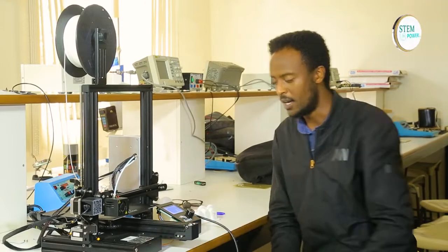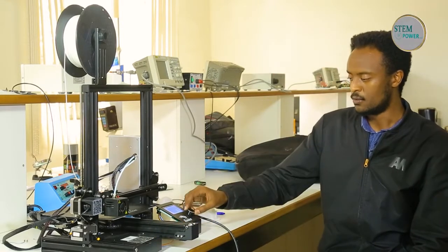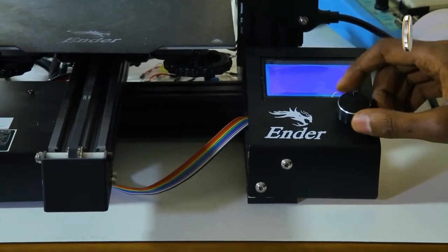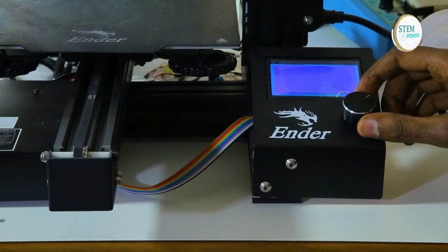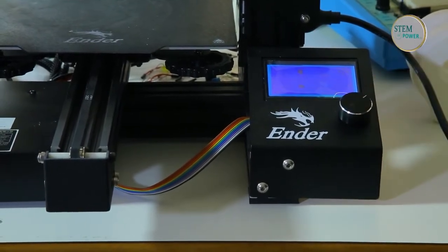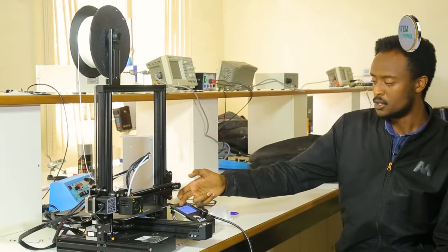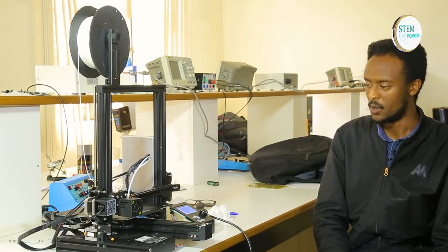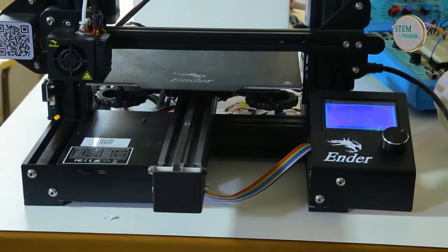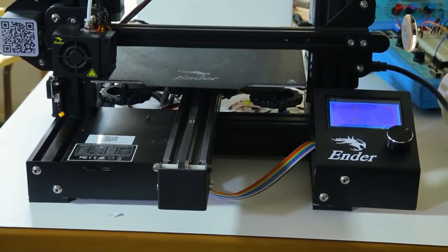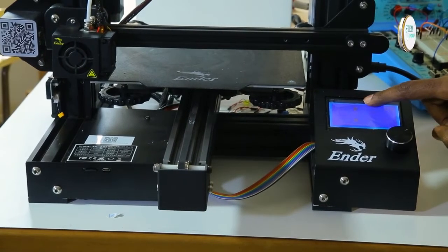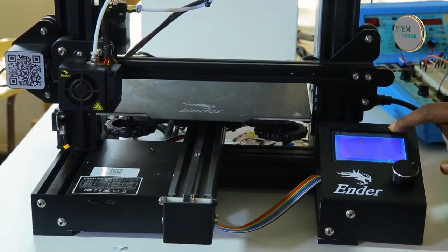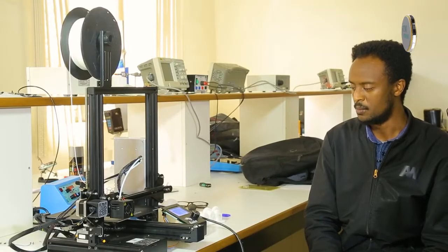We can find all the files that are stored in this SD card from this window. Now it says print from TF, that means print from the SD card. I can choose any file that I want to print. Now if I hit this one, since I already set the temperature of both the nozzle and the bed, it will start working in a while. Now you can see that both the nozzle and bed temperatures are increasing to the set temperatures. Once the nozzle temperature reaches 200 and the bed temperature reaches 60, the printing procedure will begin.